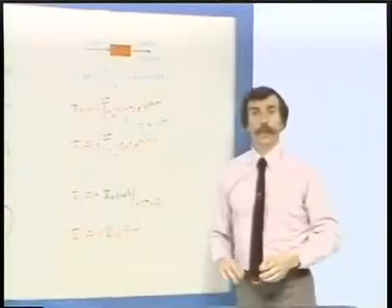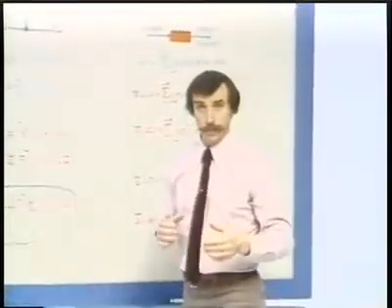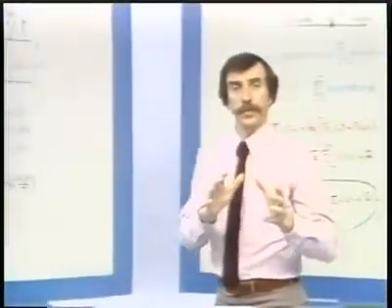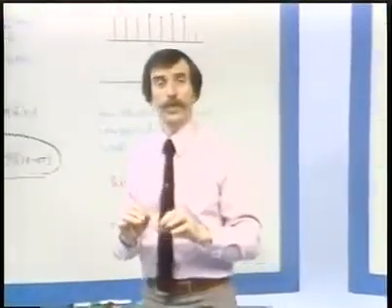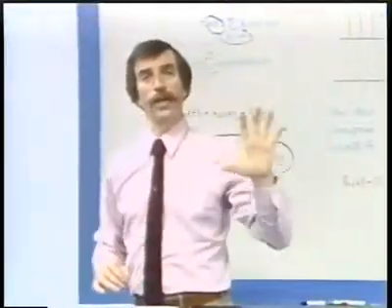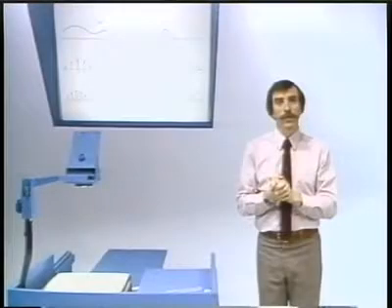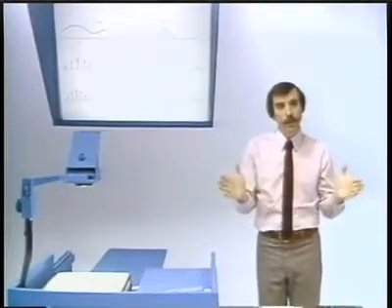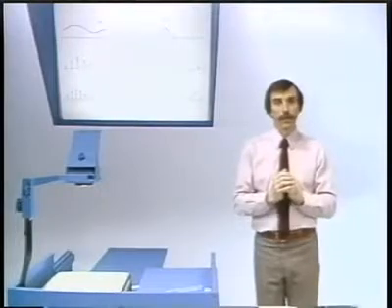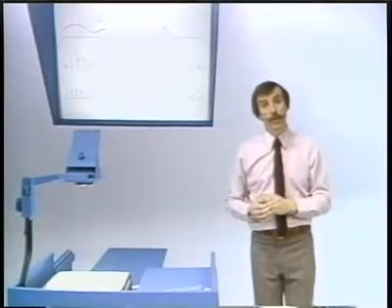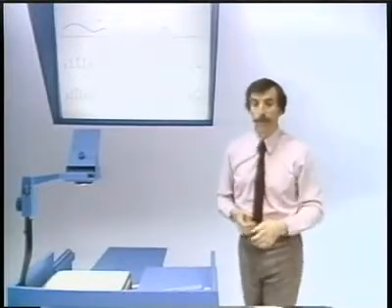All right, so we have this two-step process. The first step is taking the continuous time signal and sampling it with an impulse train. In the frequency domain, that corresponds to replicating the Fourier transform of the original continuous time signal. The second step is relabeling that, in effect turning it into a sequence, and what that does in the frequency domain is provide us with a rescaling of the frequency axis, or as we'll see, a frequency normalization which is associated with a corresponding time normalization in the time domain.